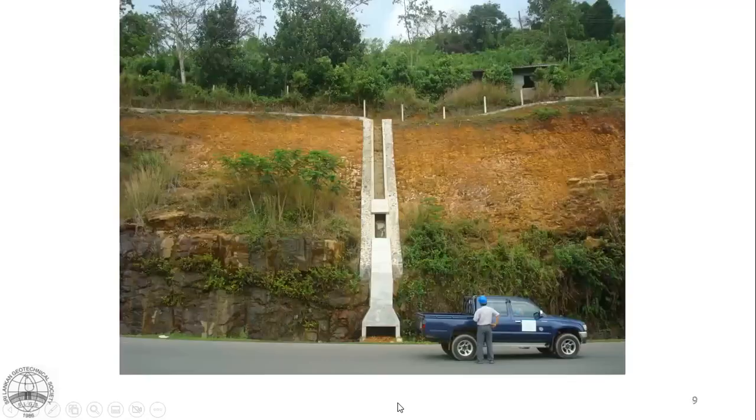or any room for leakage. You can see here the cut of the berm drain, and it is sloped into this cascade drain, and water is coming through that. So that cover is provided here to prevent water splashing onto the road surface.